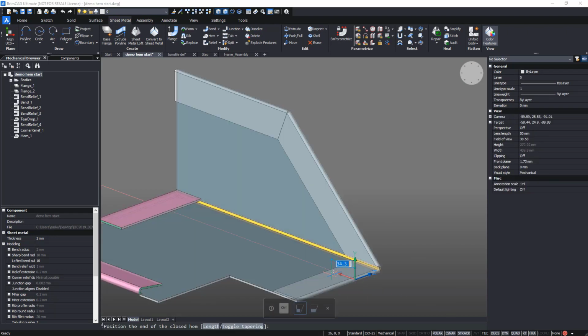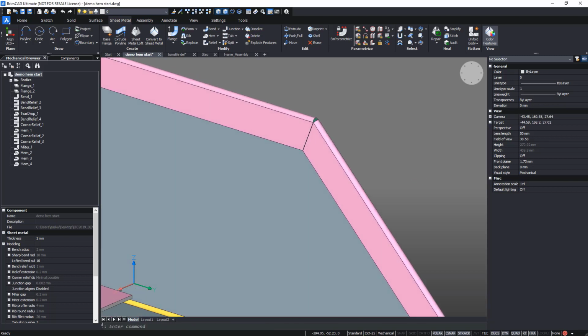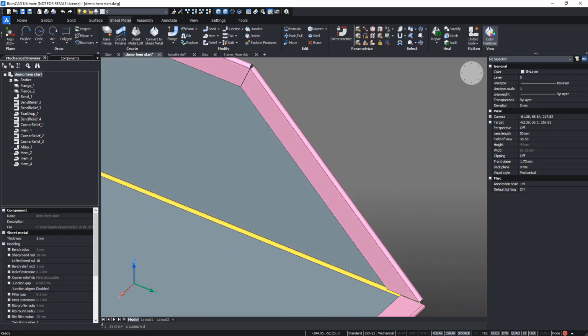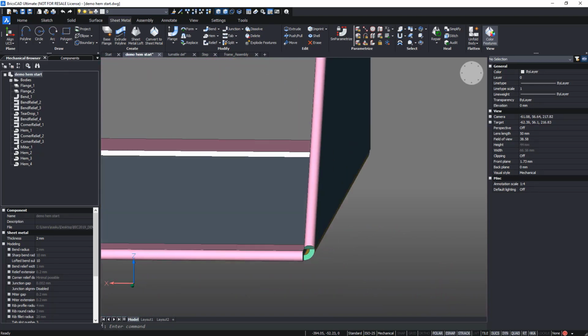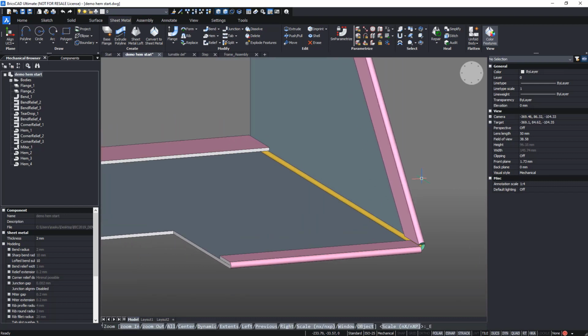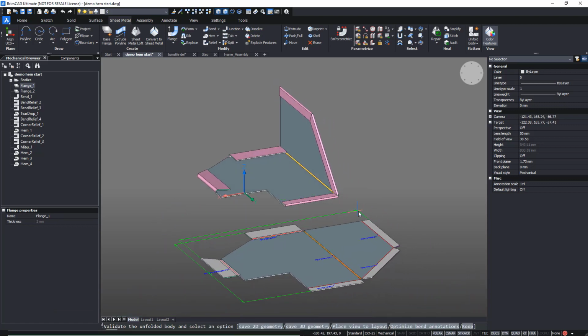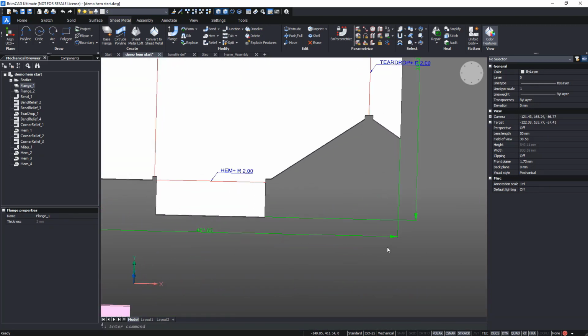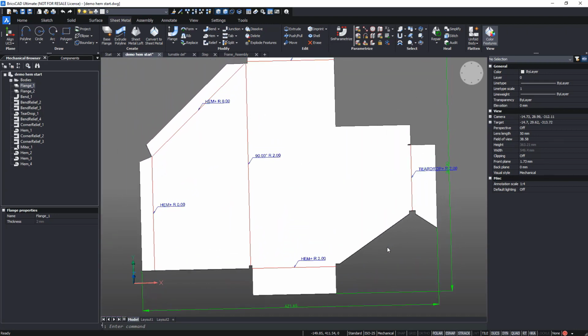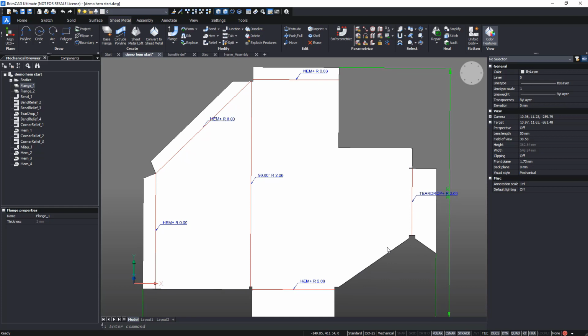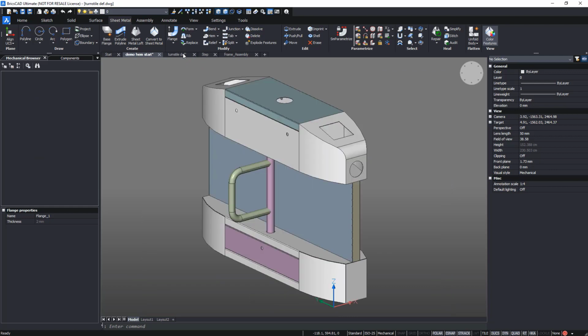You see that it's very nice because there is no collision at all. In the corner on the top there is a miter, and in the corner on the bottom the hem follows the bend lines. So there is no collision, and you can unfold without any additional job. And then you have a special annotation, which is M, the gap, and the plus or minus, which indicates if the bend is down or up. This is what we call hem and teardrop.